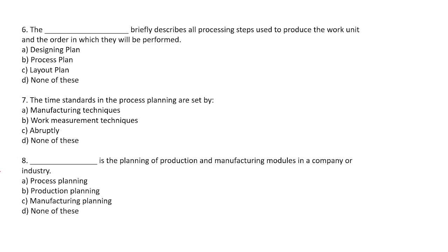By seeing the code itself, you can say how that part is classified. It is a nine-digit code, with the first five forming the primary code and the last four the secondary code. Digit one interprets the general shape of the workpiece.